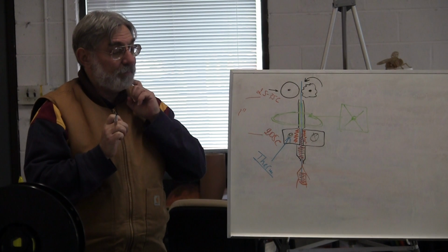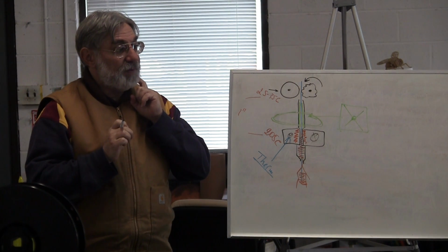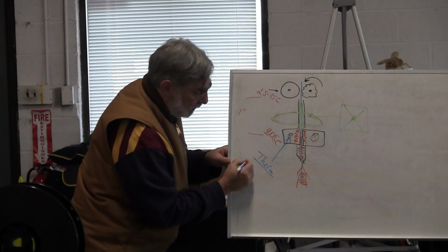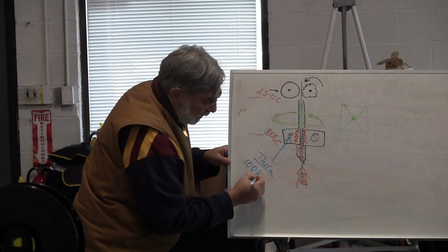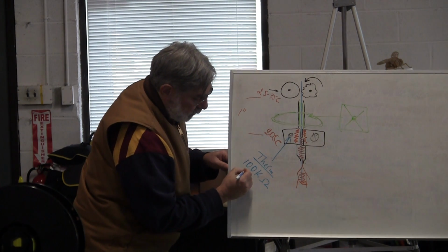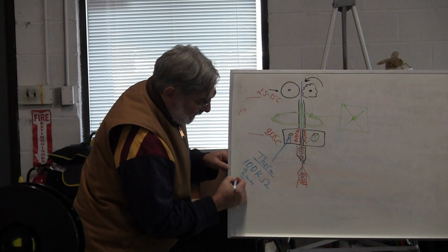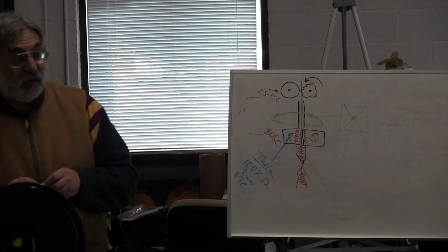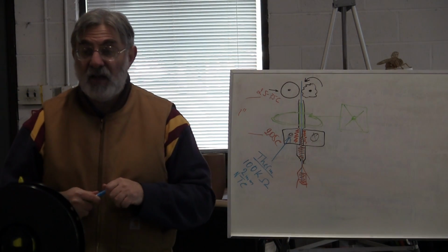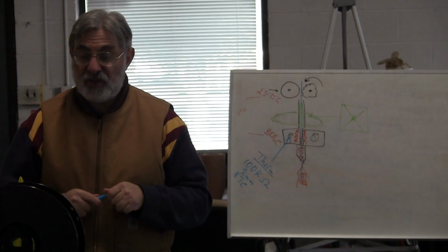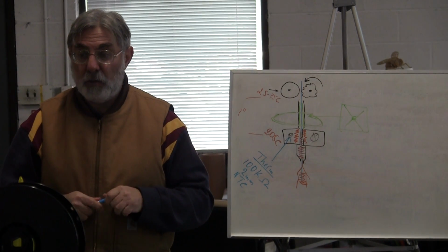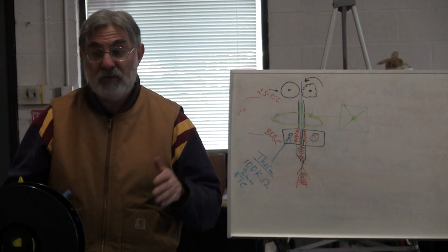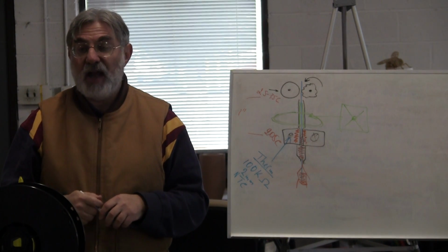Is a thermistor a standard part, or do you have to buy some specific one? You typically have to buy a specific thermistor. They're called 100 K ohm 2 millimeter NTC thermistors. They cost, I don't know, $1 each on eBay, and they're everywhere, and there's 10,000 different vendors, and you buy the cheapest one and don't worry about it so much. But we keep dozens of them around, because they're cheap, and they break down a lot.